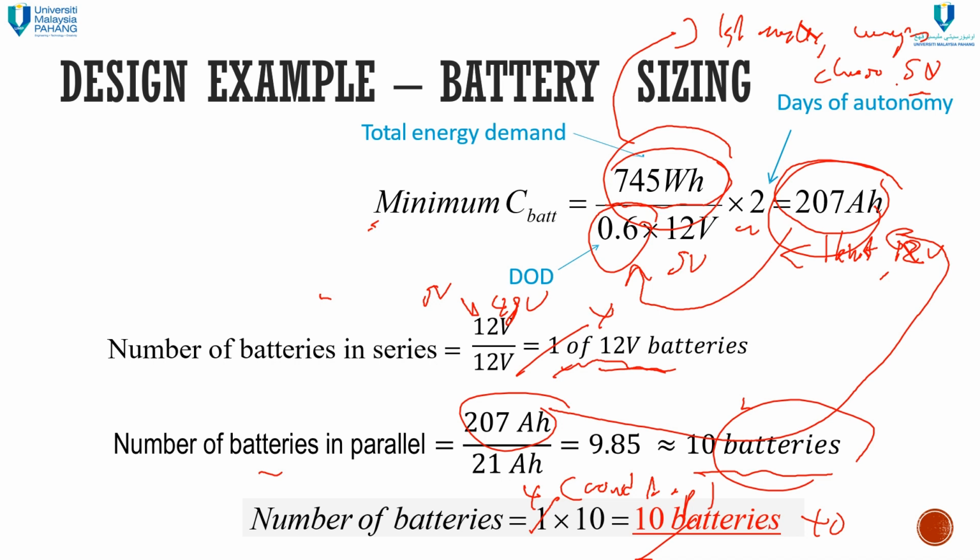Then after that, we don't consider the inverter efficiency because you use AC, and we don't take the overall general system efficiency coming from the cable, charge controller, connectors, everything. It should be 85% or 80%. What we don't consider, we treat as 100%. That's the second mistake. The third mistake, when we choose the battery, we don't consider the depth of discharge seriously.